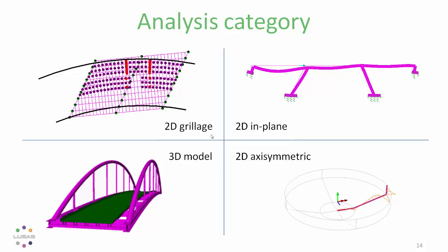For example, if you have an integral bridge, you might have soil pressures and temperature loads occurring in plane, giving in-plane forces, not just bending, but in-plane forces. And that's when a 3D model would be necessary, because you need to take that into account.